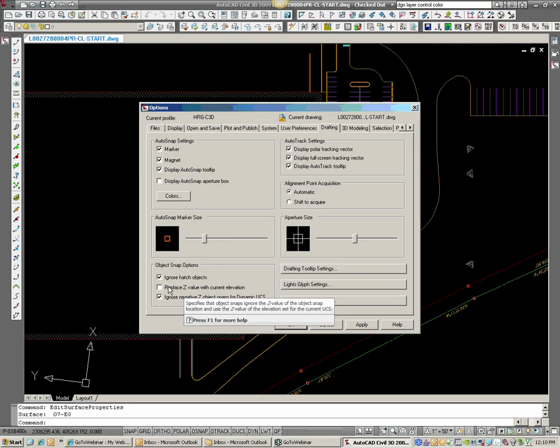just to be cautious. If you're grading in Civil 3D, to me, you're an advanced user, if you're successfully grading in the fashion I'm going to show here. And I think you can handle unchecking that checkbox. And if you don't, it's not like you're going to make a mistake and report a wrong distance to a contractor or client. You're just going to say, oh, I forgot to turn that off, and go turn it off. So that's there. Always have to uncheck that.